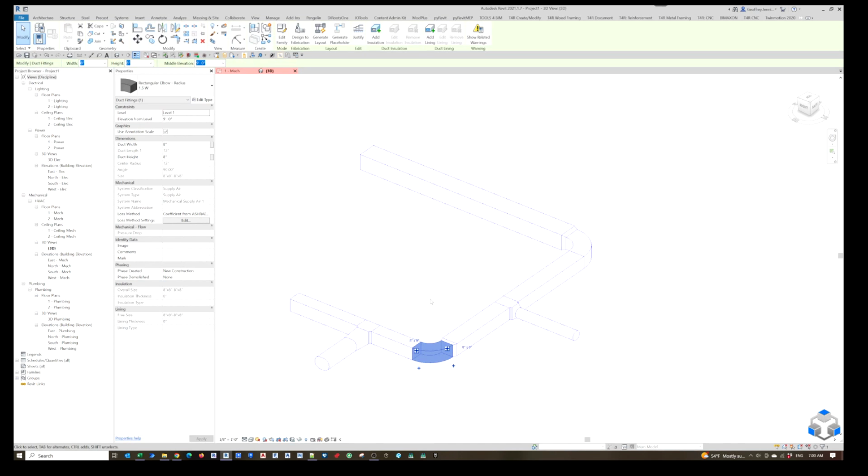So let me first go ahead and address a couple items for the mechanical duct fitting, and then we'll go into creating a lookup table. And I'll be using Family Type Manager in the process for creating all the combinations, and then the lookup table with rules of naming, then using creating the family type formulas as well too in this mechanical duct fitting. So as you can see,